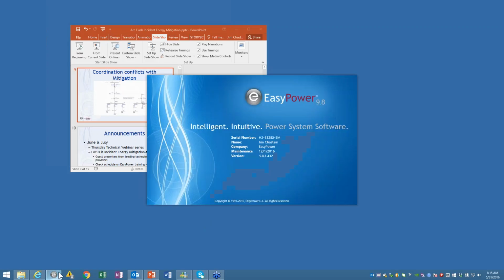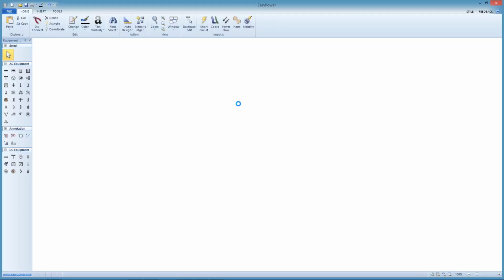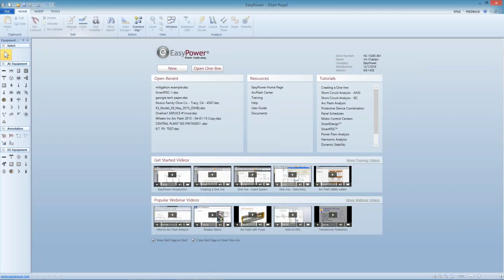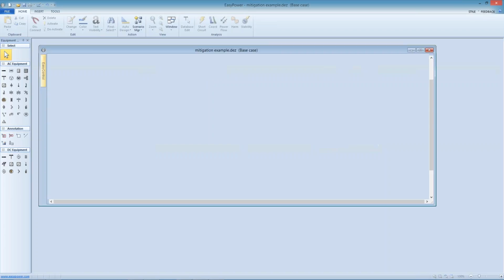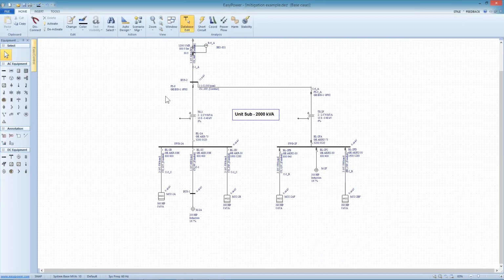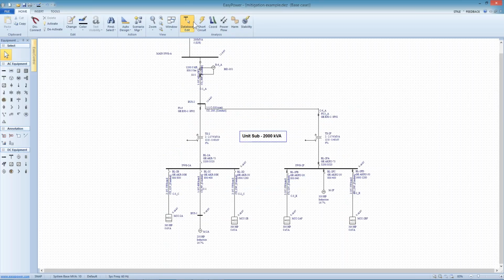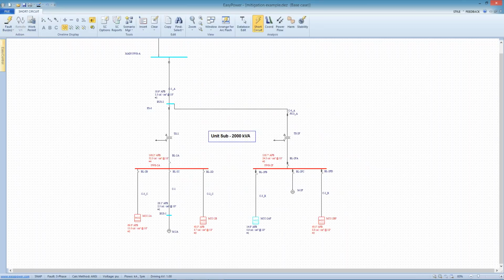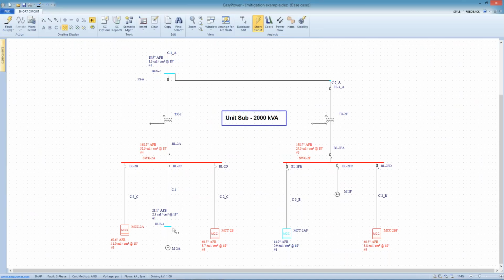One of the things that I like to point out is that just because we have a good reading, if you will, on a particular bus, that doesn't mean it's properly coordinated or even safe. The case in point is on this particular remote load, we have a nice low incident energy calculation, but everything around it is elevated, and so the question is why?